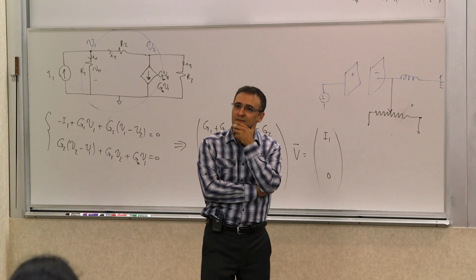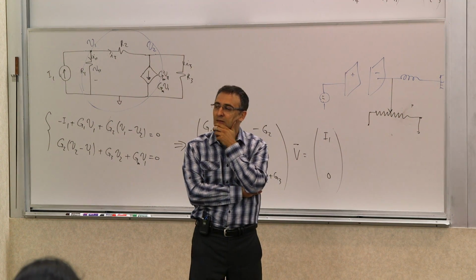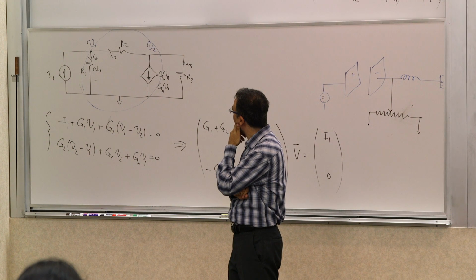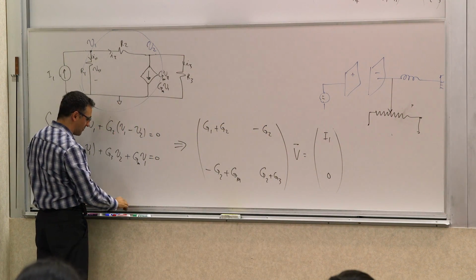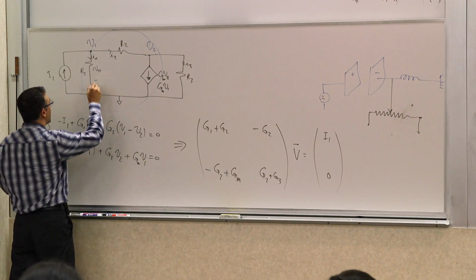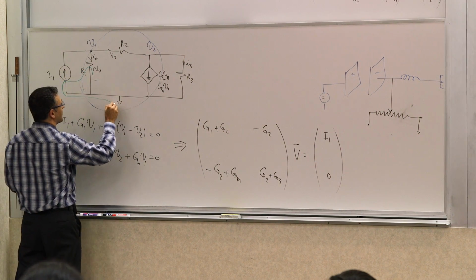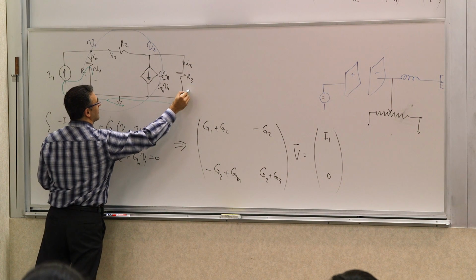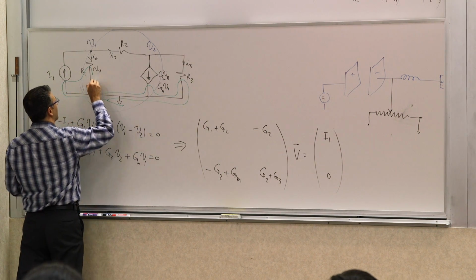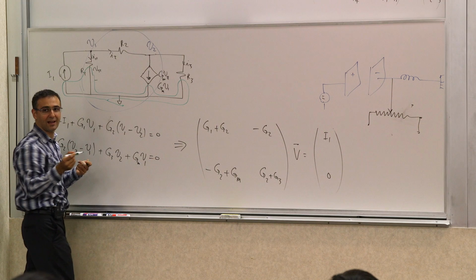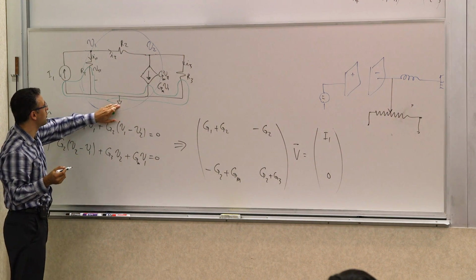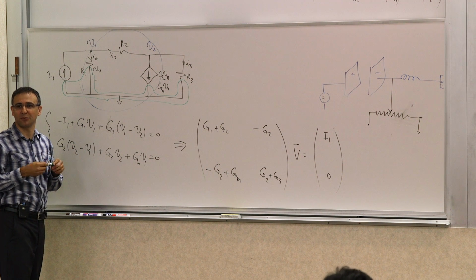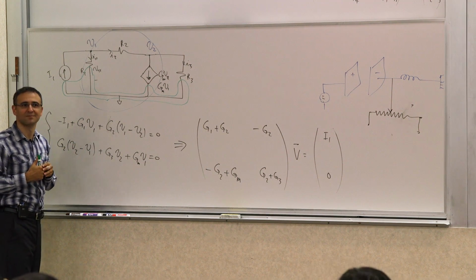Why did you put the ground on the wire? Why did I put the ground on the wire? You mean here? Yeah. Well, the way I was thinking about it is that this entire thing is a node, right? Oh, okay. Right? So it doesn't matter where I connect it. I'm attaching this, I'm making this node ground. So this is a convention of the way I draw circuits. Yeah? Yes, in the back.